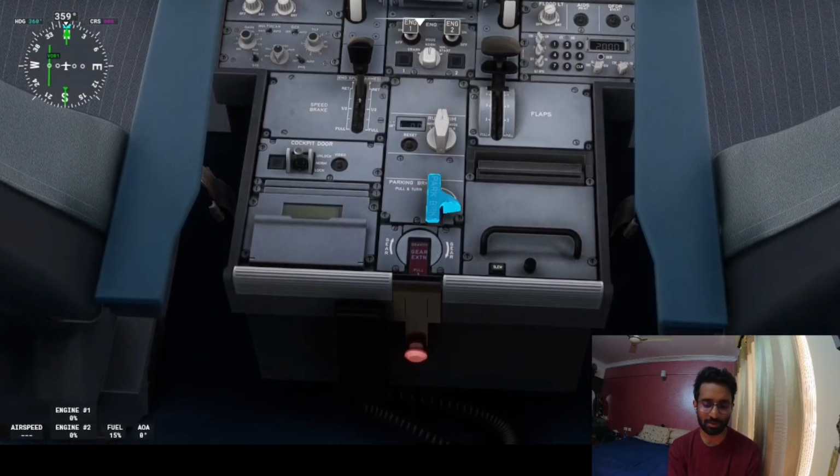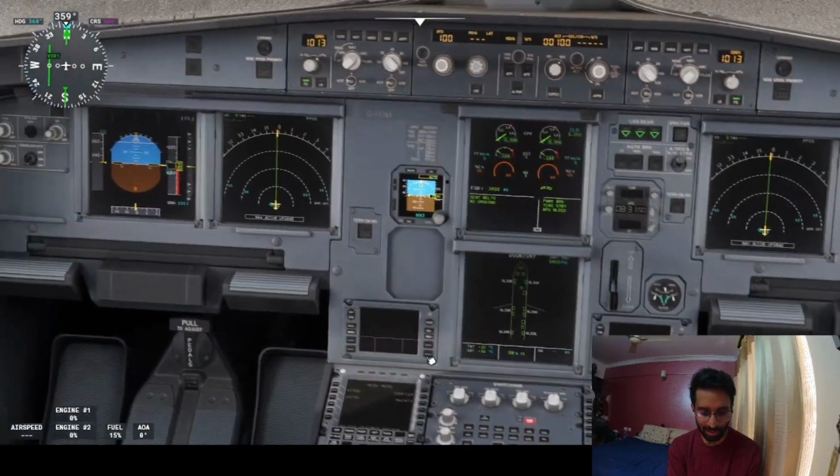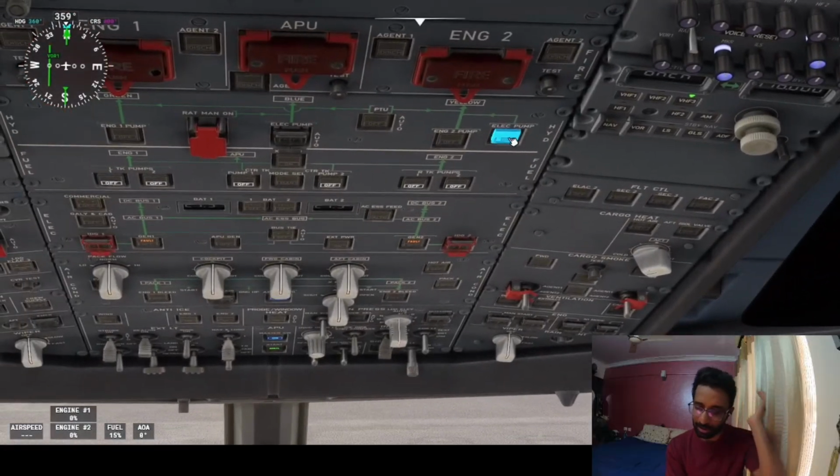Yellow pump, though we use it for the brake accumulator; blue, though, we don't use it much. Now let's see another condition. So, PTU inhibition logic, if you remember from what I had explained before. On the ground, if both masters are off and the pressure difference is 500 psi, so it's an AND condition, right? It needs to be 500 psi and both masters are off. That is this condition on the ground, right?